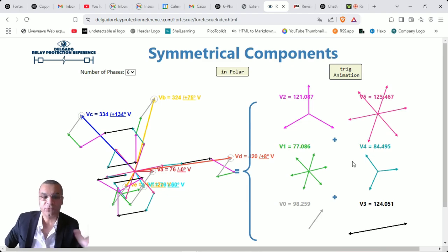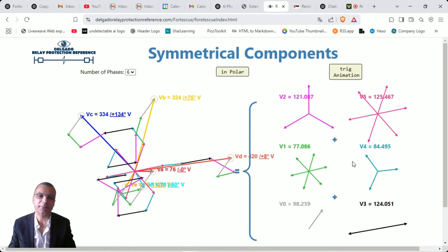So this is the animation, and obviously I'm thinking of using this tool to further understand and go deep into the distance protection algorithm and how this affects how distance faults are calculated. That's something that I will be investigating further later on. I am particularly interested in how this might influence distance protection, but I personally believe that line differential protection might be a better solution here, especially since most manufacturers already provide line differential schemes for breaker-and-a-half, so you'd have all the analogs readily available, and that would make protection quite easy to implement, actually.